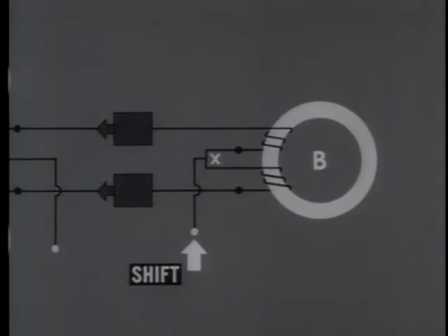It will occur when a shift pulse is applied to the split winding and divides unequally into a small upper branch and a large lower branch. This is very much like the split winding loop itself, but the inhibit loop has a different way of making the branches unequal, as we shall now demonstrate.